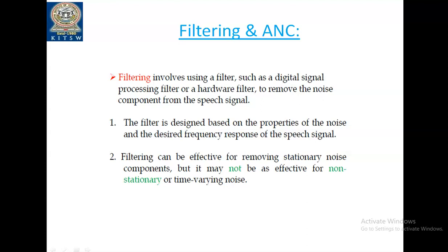So when you see the ceiling fan, the sound that is coming from the ceiling fan is stationary. It is not a time-varying noise, so that is a stationary noise. But the filter that you have already designed is best suited for removing stationary noise, and it may not help that much for non-stationary noise, because speech is non-stationary. But when you record any kind of speech, we initially divide it into frames with a duration of 10 to 20 milliseconds.